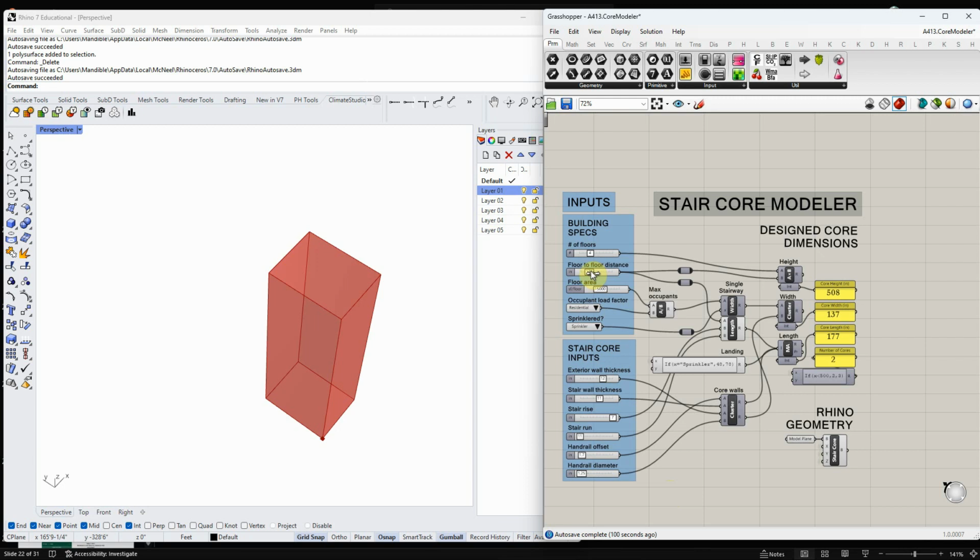And for example, this floor to floor distance is going to be related to your HVAC system, because if you have ducting or you don't, and the size of the ducting. And we're going to do a script later in the semester to approximate that based on some decisions we're going to make about HVAC. So we could be using that right now too. Anyway, so these are inputs that determine essentially right now the number of floors and the floor to floor distance is determining the height of the stair core. And so you just saw me adjusting those and how that adjusted our core out here.